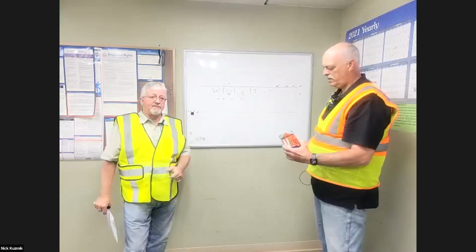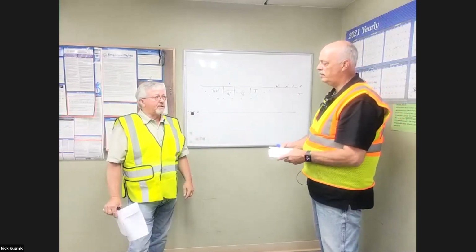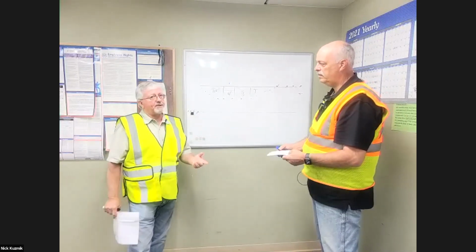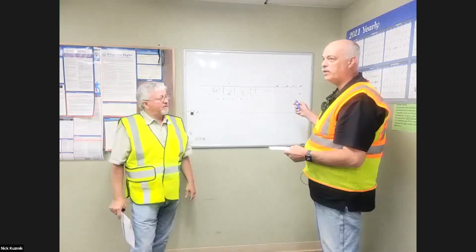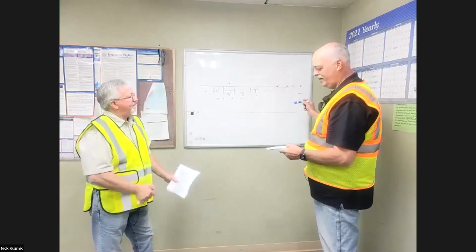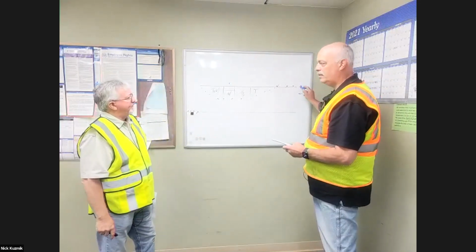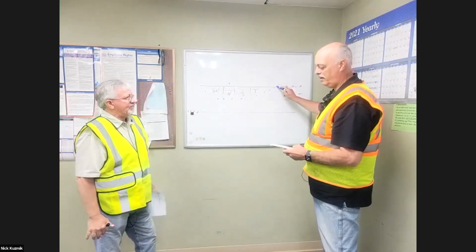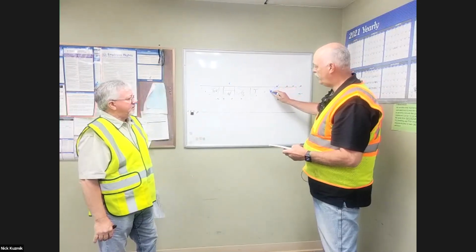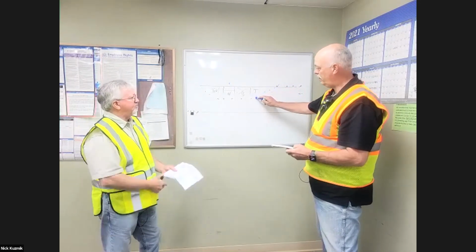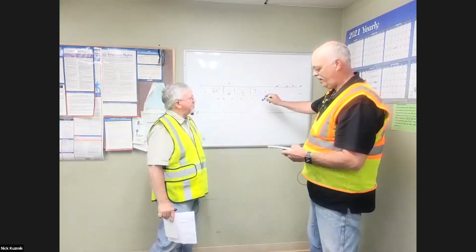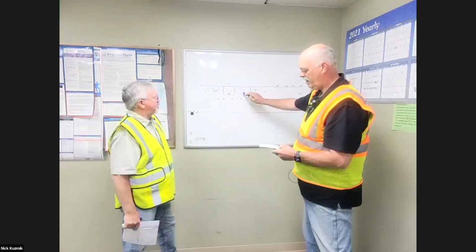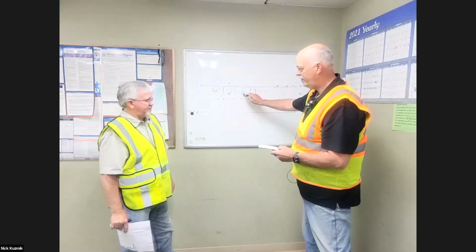The flagger itself is going to be there to help answer questions, guide traffic, stop them when they need to be stopped. Let's just go through this real quick one more time so everybody got it. We're going to do 3 signs, right? Flagger, and then we're going to do the advance warning. The signs are the advanced warning. Okay, and then the transition. That's the transition. The taper. And then the buffer zone. Yes. All right.